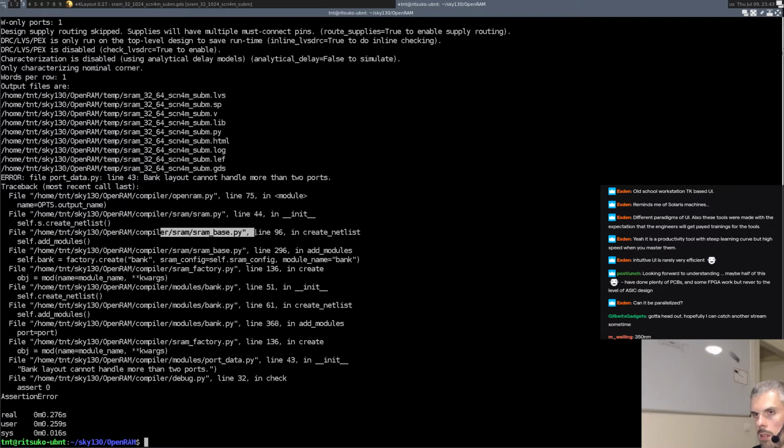It might be interesting also to see if you can generate memories using the standard cell libraries and using directly flip-flops or latches, which might be smaller, using the OpenRAM infrastructure, because you can totally generate a flip-flop only memory, and it will generate a bunch of flip-flops and all the associated logic, and then you feed it to the automatic placement and routing.